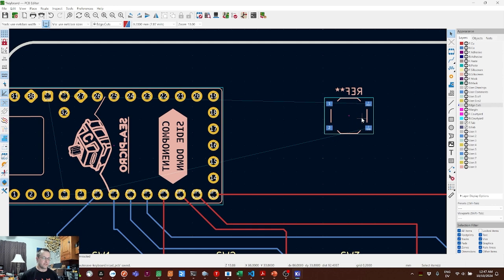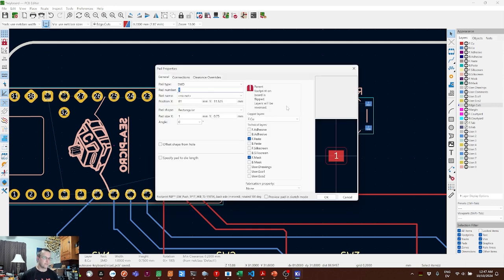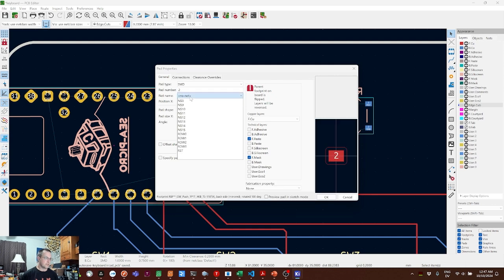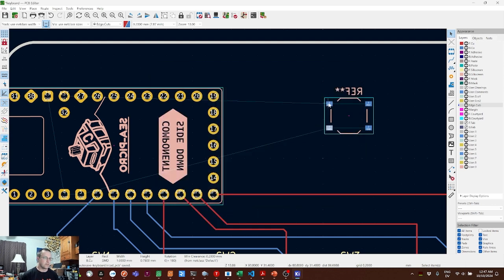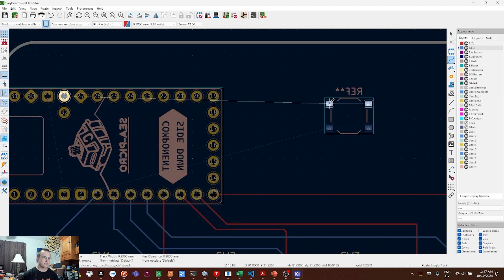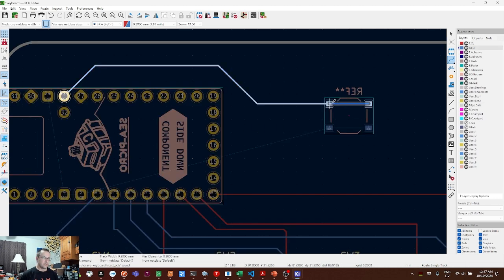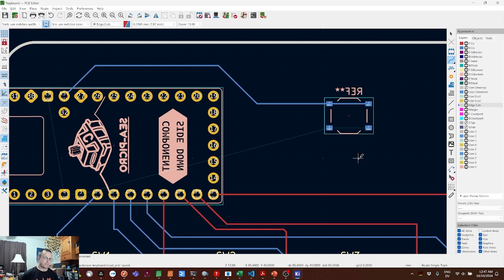All right, that also means that we want to set the net for this side. I guess there's no reason we can't make longer traces for it. But I'm going to connect this side of the switch. All right, hit X to start a trace, and we'll go from the reset side of the switch to the reset pin. And why not? We'll connect the 2 sides of the switch together.